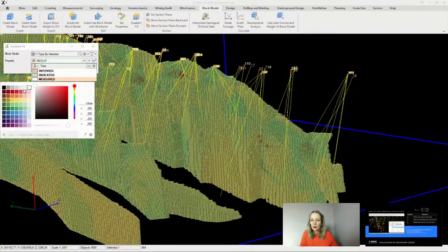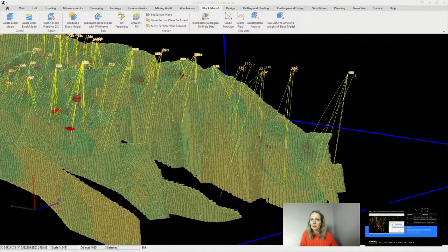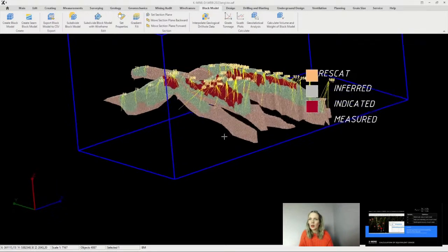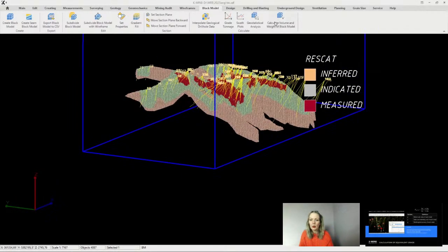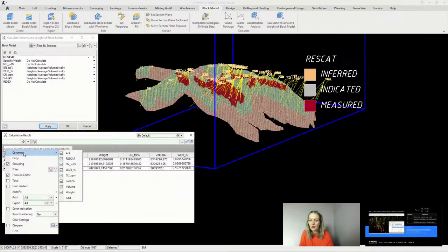In the result window, you will find a built-in formula tool for performing recalculations. So for instance, let's add a column and calculate the amount of tin in tons within the ore. In the formula field, we input equal tonnage multiplied by grade percentage divided by 100,000 tons.